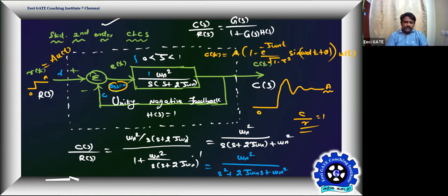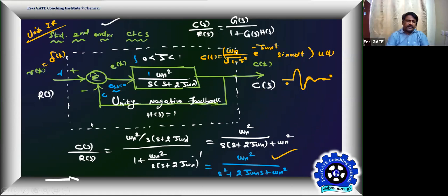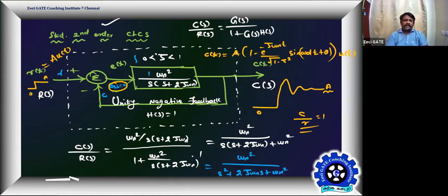Steady state error here also is 0, because at t equal to infinity input is 0, output is also 0, then error is also 0. That integrator is responsible to make that error 0. Here also the integrator is responsible to make the error 0 for step input. But if you apply a ramp input, error won't go to 0, for a reason. We'll see that in steady state error analysis in one more subtopic later in this unit.